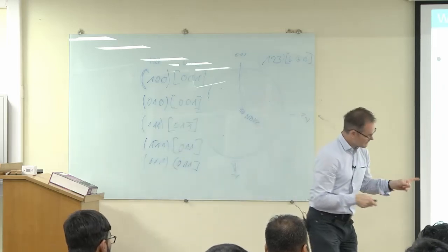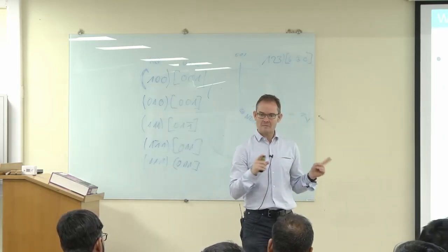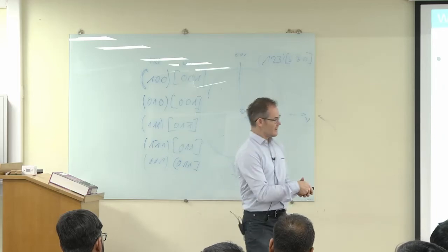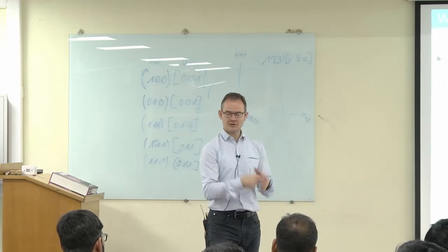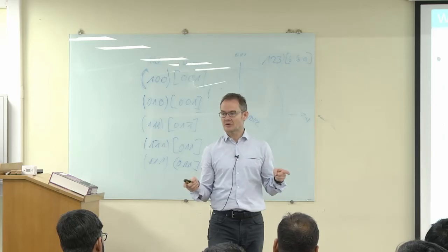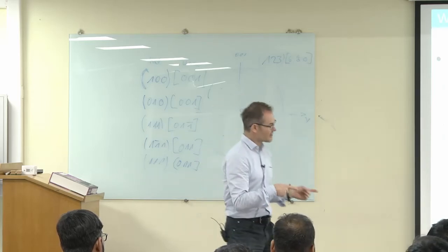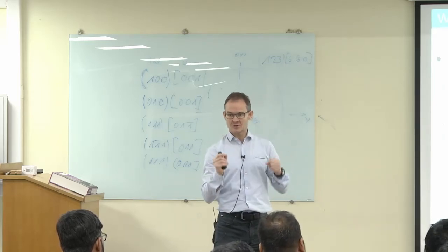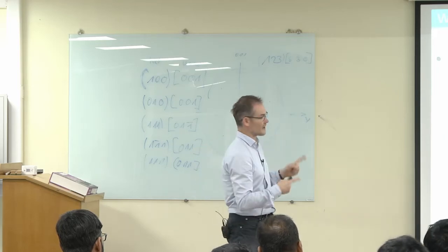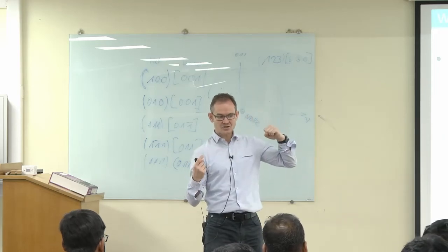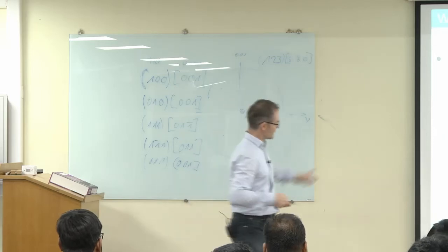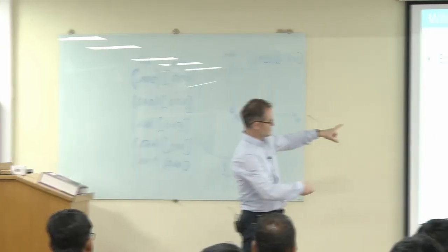And in order to optimize this, we need to know one thing: the magnetic flux is not going through a material without resistance. Depending on the crystal orientation, you have a high or a low resistance, you have a hard magnetic direction or you have a soft magnetic direction. And this is plotted here.